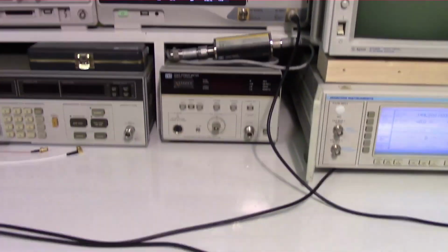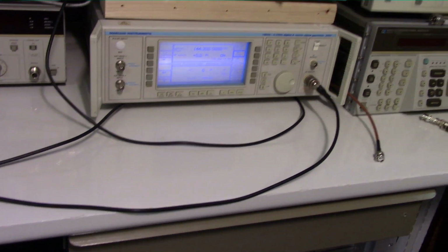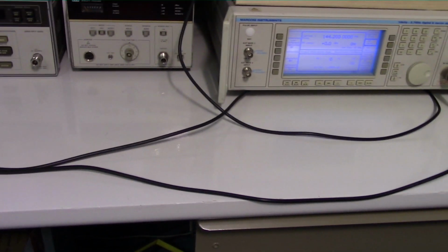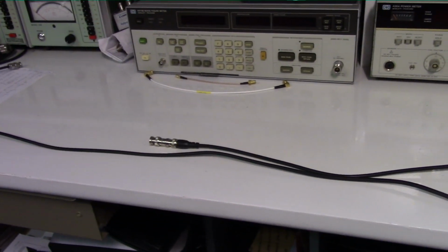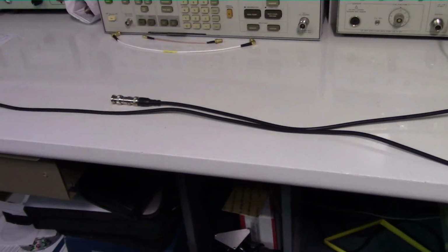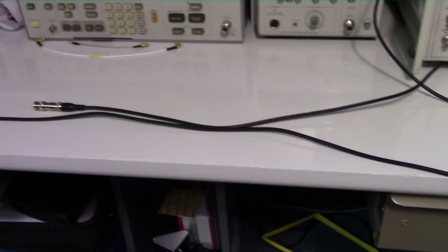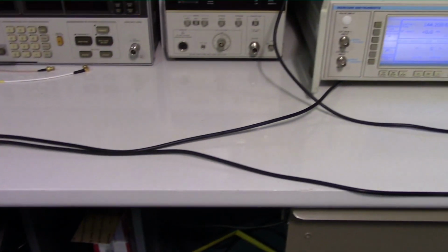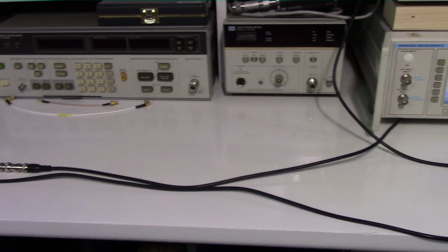So okay, let me get this put into the rest of the video. I just wanted to explain to you the importance of the layout: starting out at one end, putting your step attenuators in the middle, and then putting your rig over on the other side, and not being messy with your cables and letting them be close to one another. Especially don't put them parallel together the way I have here. That's the worst case scenario. And by all means use good quality cables.